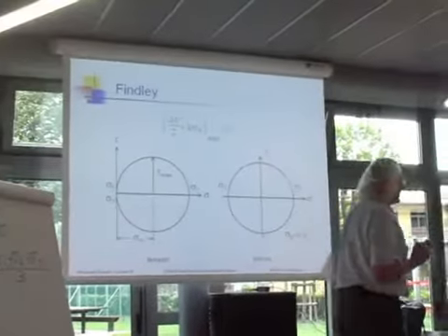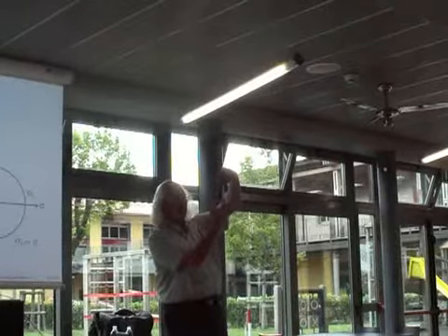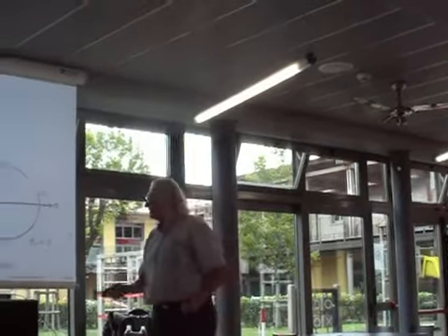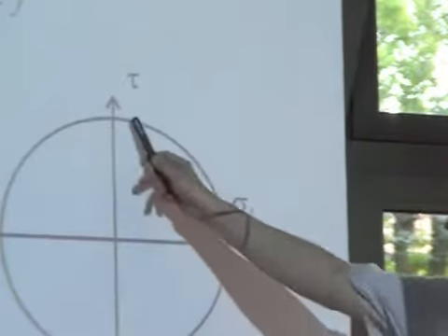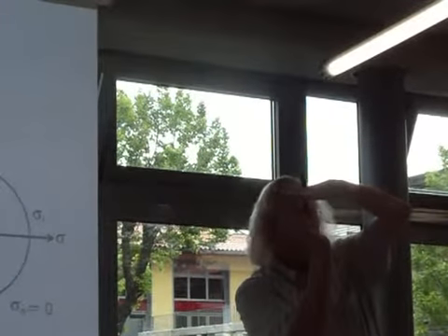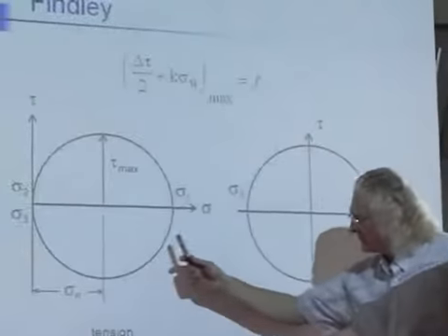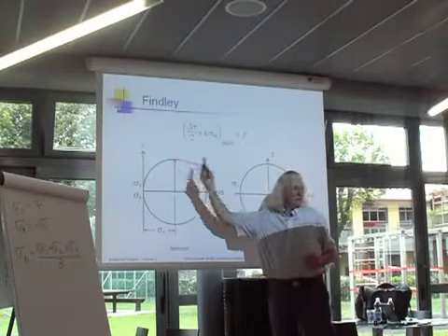And now let's look at torsion. So I'm going to twist this now with the same shear stress. Right? But when I look at torsion, okay, I have the principal stress and the shear stress is equal to this principal stress. Fine. But on the failure plane, on this plane, the normal stress is 0. So if we think about the picture we are developing for how the fatigue process works, this should be much more damaging than this for the same value of the shear stress.